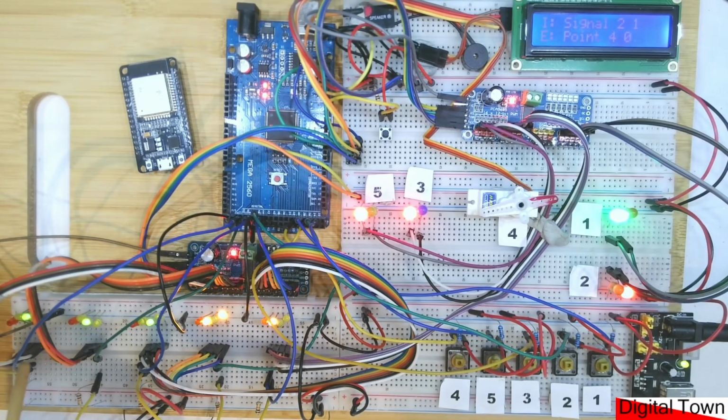Down in the bottom left hand corner, I've got my block signaling. Now, as I've said, I'm using 4-aspect UK. So that goes green. We then go to double yellow, single yellow, and red. Now, if we imagine our train is moving along the board, as it goes through the first signal, you see that that signal then goes to red. As it goes into the next block, obviously the next signal goes red, and as the back of the train clears the first block, that signal will go to yellow.